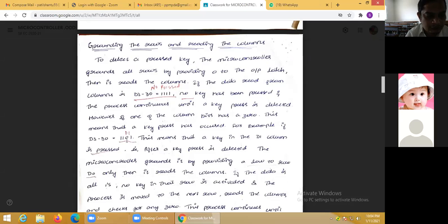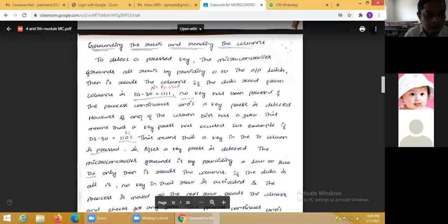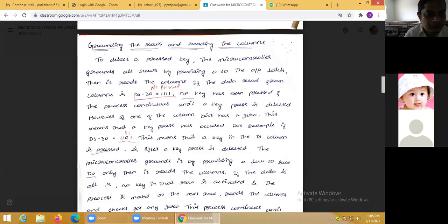So we are using the active low logic, meaning common anode. All anodes are grouped together and connected to 1. When we give 0, that particular segment will glow, meaning we are making forward bias. Keep in mind this is a diode and we have to make forward bias. Similar to this, in a keyboard we have D0 to D3 arranged. If no key is pressed, all are 1, 1, 1, 1, meaning active high.